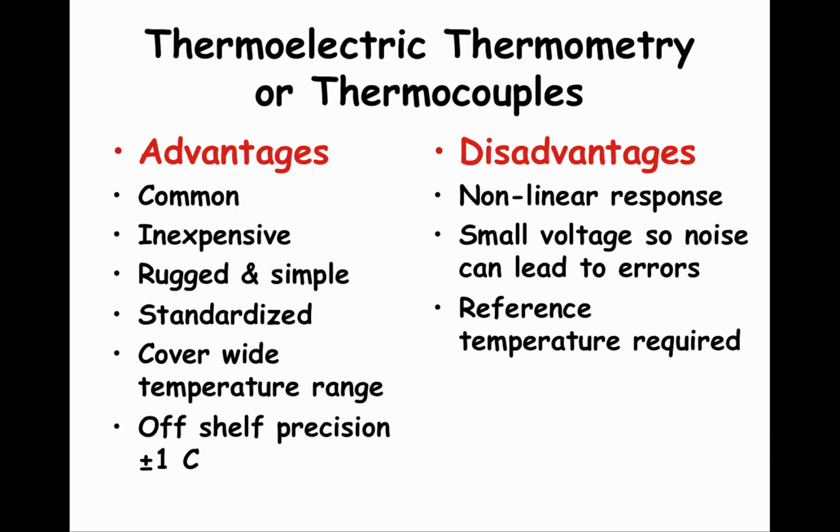We generally prefer sensors that have linear relations between the input and the output, but thermocouples have nonlinear relations. So the relation has to be found and used. Finally, thermocouples require a second reference temperature input. We will talk about reference temperatures more later. So while thermocouples are common, the disadvantages need to be overcome.